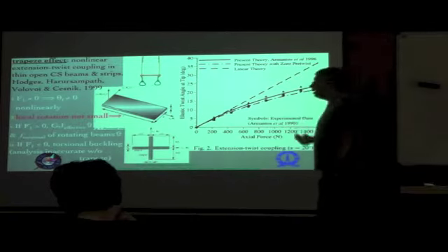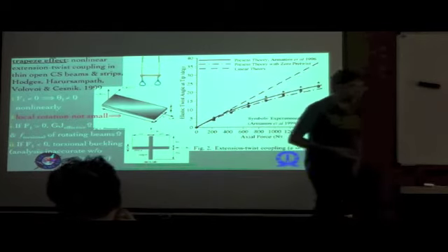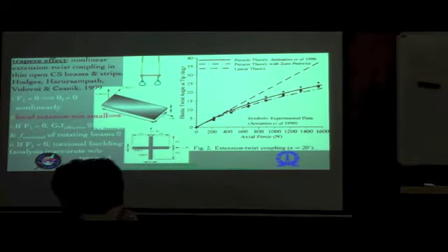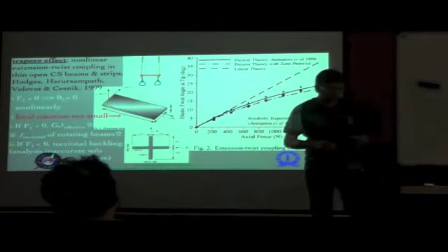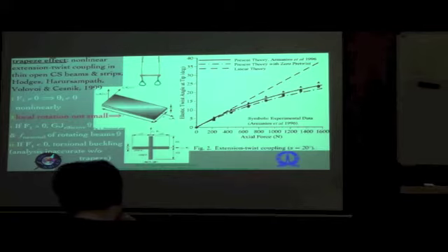Next, if you look at the axial load being negative, obviously it is compression. You're all familiar with buckling, which is flexural, but there can be another type of buckling which is torsional. It typically happens with cross sections which are torsionally soft. In other words, the torsional stiffness is much lower compared to the bending stiffness.